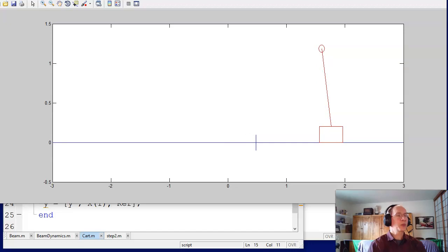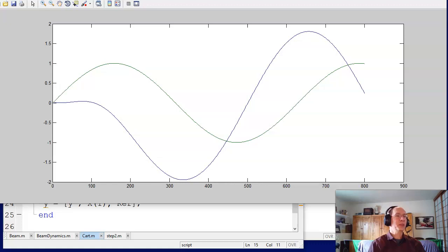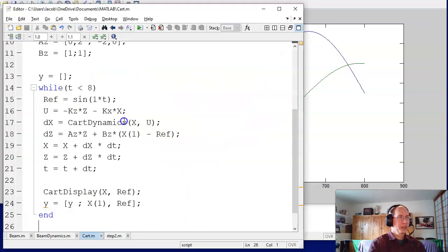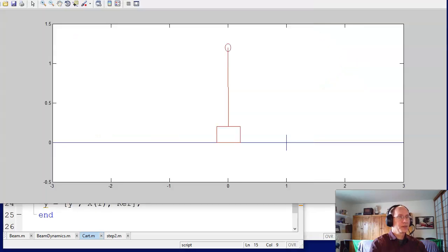What we'll look at next is what happens if I have both a constant and a sinusoidal disturbance. That'll be the generalized servo compensator. That'll be our next lecture. With this system, if you apply a step input, it won't track. Again, it's not designed to track a constant, it's designed to track a sine wave. If I give it a different frequency input, like DC, it'll do something, but it won't track. That'll be our next lecture, generalized servo compensator, if I have multiple frequencies, such as a constant and a sine wave. That's lecture number 17, servo compensators for AC inputs, for ECE 463, modern control.